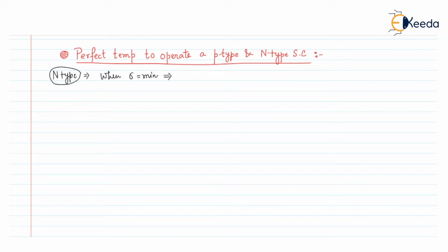when the conductivity is minimum, at that case the electron concentration, that is the value of small n, is equal to Ni root over mu p, that is the mobility of the holes, divided by mu n, that is the mobility of the electrons. Now similarly, we can find the value of hole concentration in the n-type material when the conductivity is minimum, which will be equal to Ni root over mu n divided by mu p.